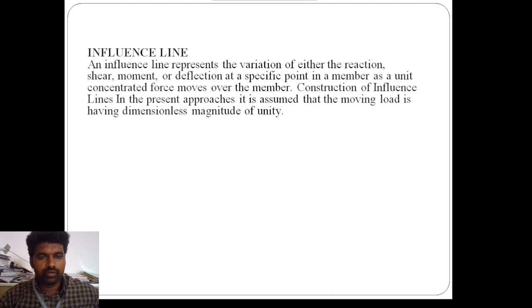That means for a point load, the calculation of shear force is load into ordinate, and for bending moment also, it is calculated by the same formula, load into ordinate. But in case of UDL, it is load into area of the diagram, for shear force and also for bending moment.